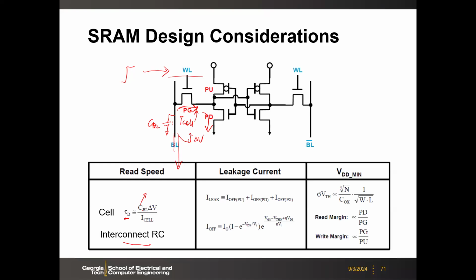So the typical array size for SRAM, of course, depends on the levels of the cache, right? Could be as small as like 32 by 32. For the larger size, maybe not as large as 256 by 256. So you can have different choices in between. But it's very rare to see the SRAM to be like 1000 by 1000. Okay, 1000 is 1024 by 1024. That is like 1 megabit.